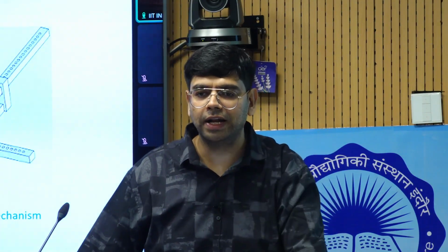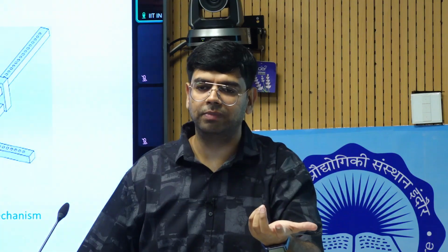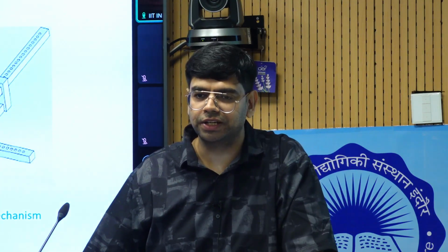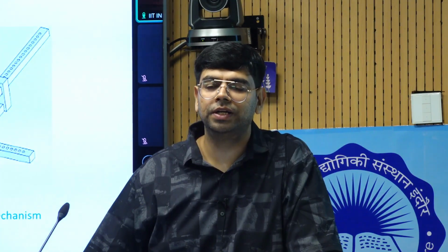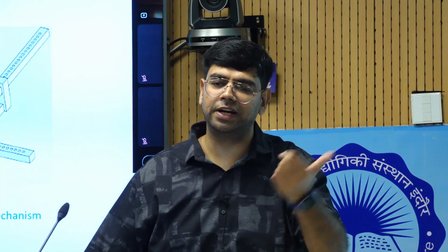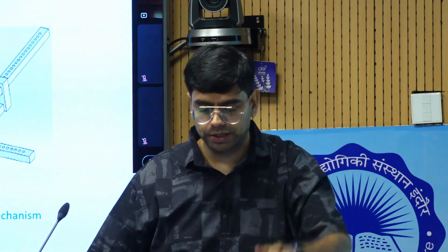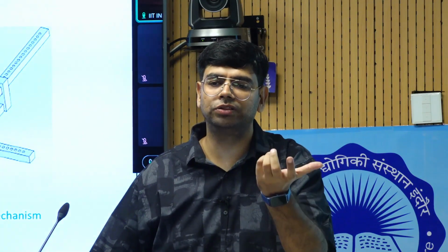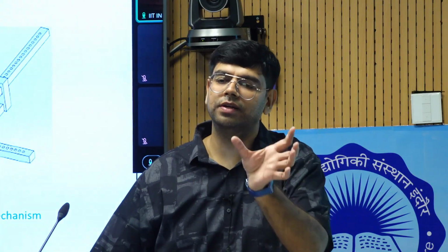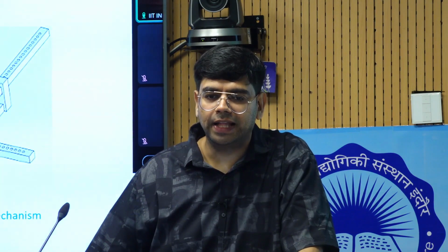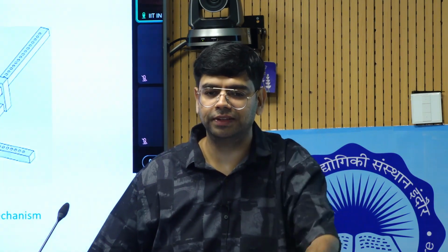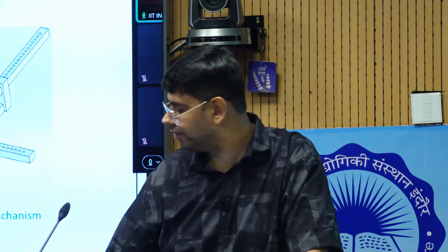Before going into that, since we are dealing with the stretching mechanism, can we show this stretching mechanism? This is very, very simple. For a square, a simple membrane, it's very easy to get the stretching. But if we are working on the radial stretching mechanism, you see that radial stretching plays a very, very important role. Yesterday, Professor Prashant Saxena showed that because of the radial stretching, after the application of the voltage, wrinkles will be developed. So radial pre-stretching is required when you are developing some circular type of membrane. In that case, it is very difficult to stretch radially. So for that radial stretching, we have developed the fully automatic stretching mechanism we have here.